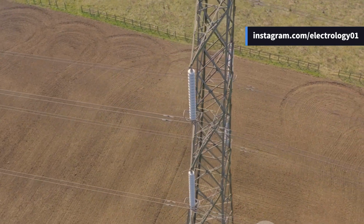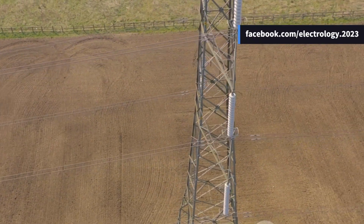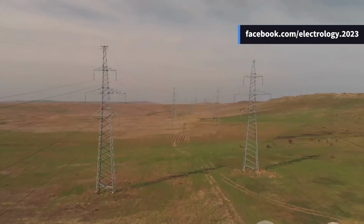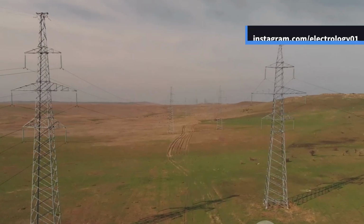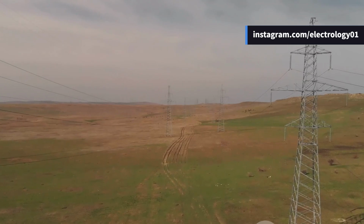Now comes the real twist in the story. The performance of a transmission line does not depend only on resistance and reactance. It depends heavily on something called load power factor. Power factor decides whether current and voltage are walking together, or one of them is dragging its feet behind. And this power factor directly affects voltage regulation and efficiency. Let us talk about voltage regulation first.